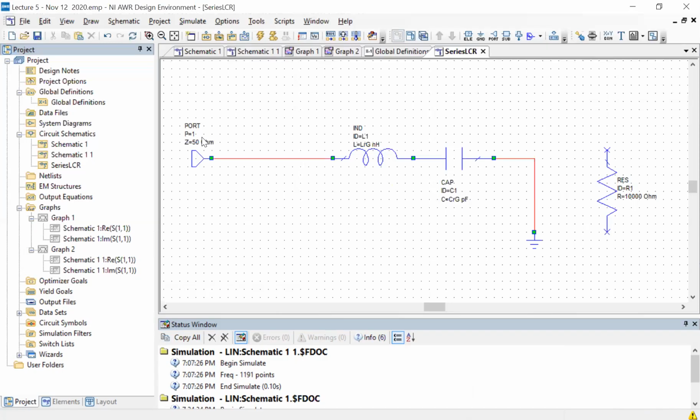Okay, great. So now if I look at the reflection coefficient and the associated properties, it's going to be different because the Z of LC is now going to be the series combination of L and C. So it's going to be j omega L minus j over omega C, right?